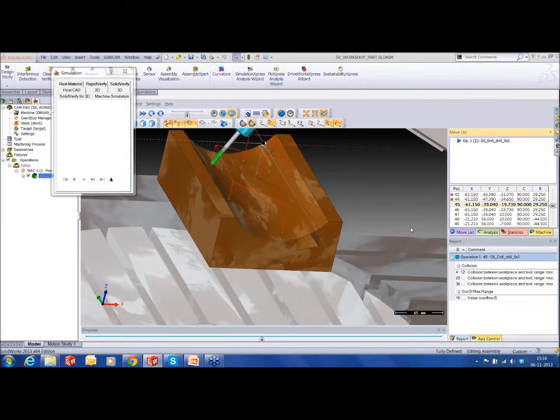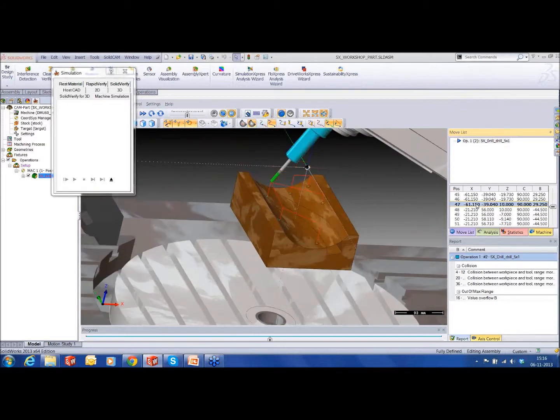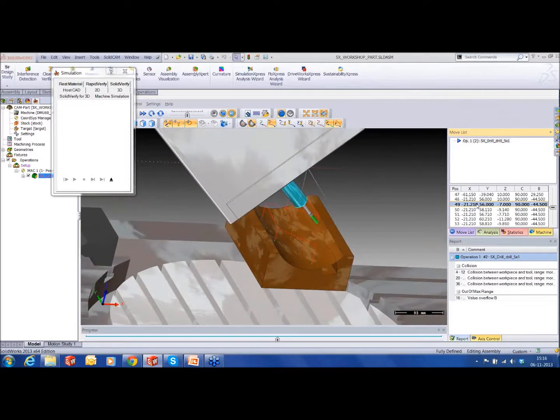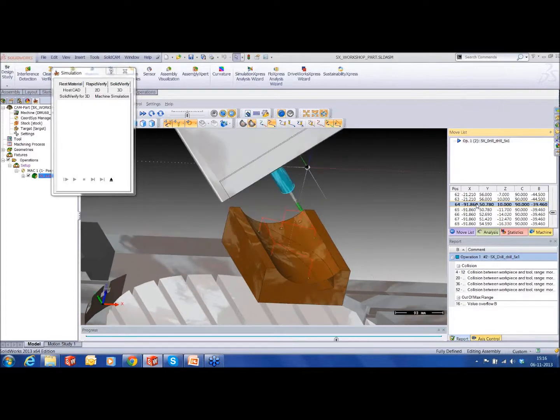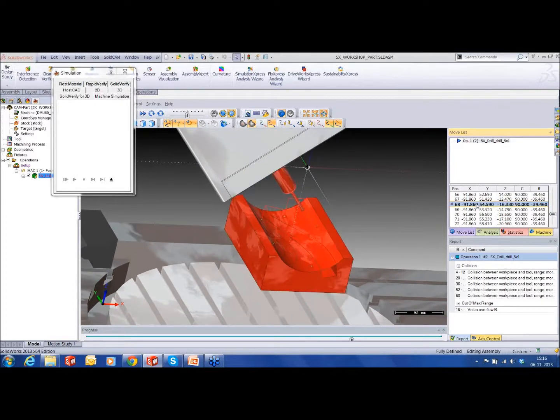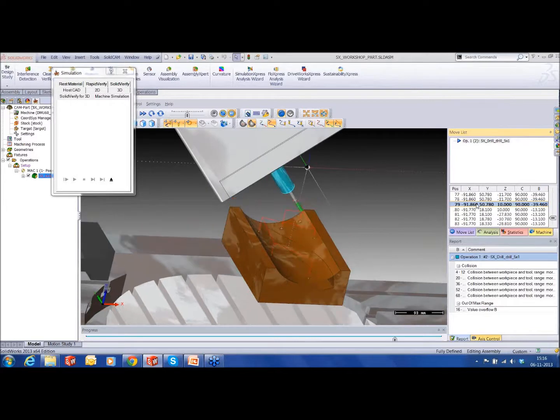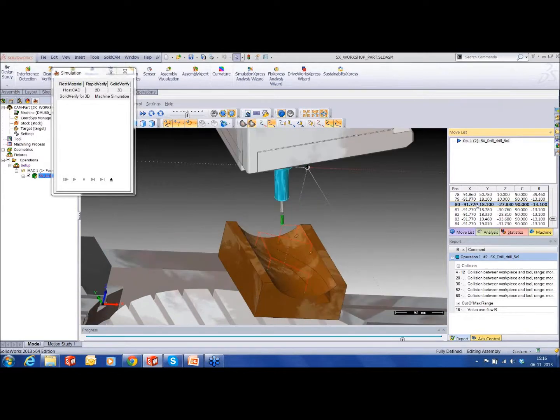It's now going to retract to the next hole out here, and it's machining, retract, next hole. I didn't specify the angles. The angles have been found directly by the software using the vector directions of the holes.